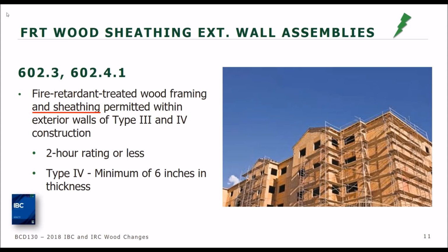I also wanted to take this opportunity to point out that it's worth noting that the reference to the minimum 6-inch thickness remains, even though AWC proposal G184-15 was approved as submitted, and that deleted the reference to a 6-inch minimum thickness. Another AWC proposal, G179-15, was on a different topic that retained the 6-inch minimum provision. When being correlated, the change that was approved as G184 was lost.